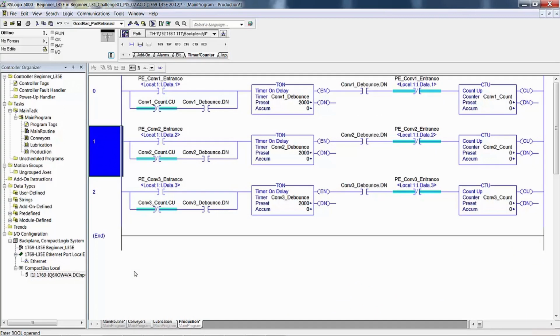If you imagine a carton on a conveyor that starts and stops and jerks, and maybe when it comes off of one conveyor onto another, that it tips a little bit. Let's say the conveyors aren't exactly lined up perfectly level with each other, even level. So the carton bobbles a little when it first gets into the photo eye. So it could break the photo eye and then tip backwards a little bit out of the photo eye and back in the photo eye. I call that object bobble or carton bobble. Wiggle. Call it whatever flips your switch.